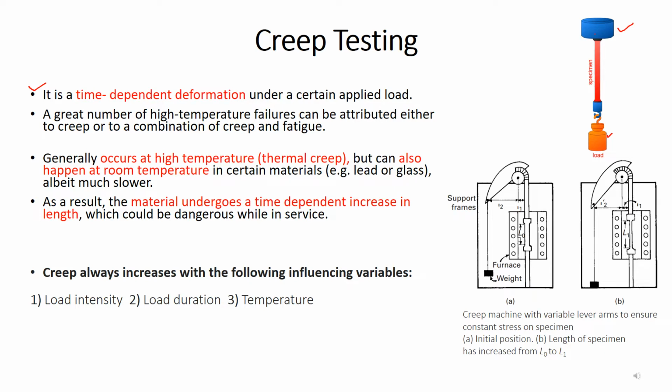But it has been observed that if you apply loads which are well below the elastic limit and you keep that load for a very long period of time, then those loads also produce plastic deformation inside the material, and this phenomenon is known as creep.